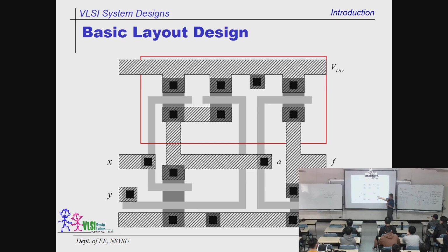In this layout, you will get a lot of information: the size, the connections, and you see a big red rectangle. The big rectangle covers all the transistors that it encompasses. If you don't have this red box, you cannot tell the difference of these two. Right now, because of this red box, we understand, and all the process engineers in the foundry understand, they are two different transistors.